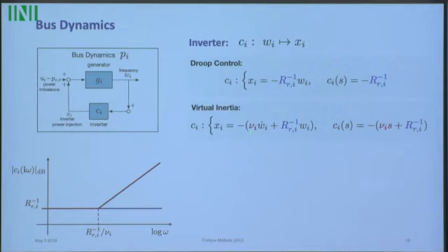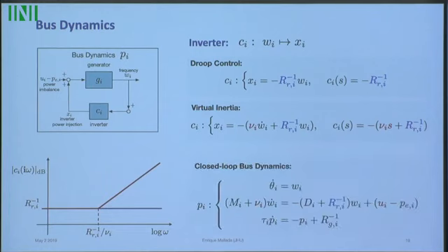So these are my models, and once you put them in the loop, you can see why, in a simplified stylized model, we call this virtual inertia, because essentially it adds mass, and why we call this Droop control, because essentially it adds to the damping. And because inverters are fast, it doesn't go through the turbine. Any questions about this model?